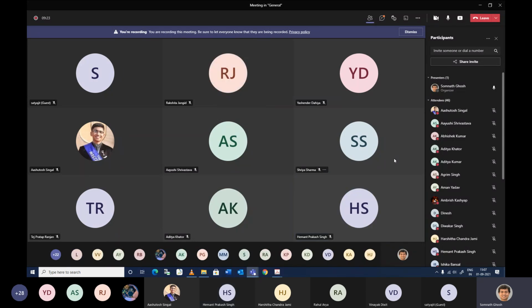And from the velocity component, which is the bulk flow of the fluid, from there you get the convective terms, right? And also for unsteady flow, you get the temporal term, this del u del t, right? So those terms are there. And if you consider inviscid flow, in inviscid flow, which term will be neglected? Anyone?